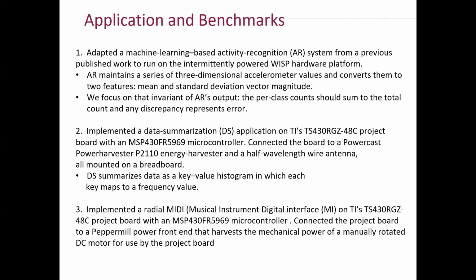In order to test DINO, we need some applications and benchmarks. In this paper, the authors have used three benchmarks. The first is a machine learning based activity recognition system, which they took from previously published work, and they run this on the intermittently powered WISP hardware platform. The WISP harvests radio frequency with a dipole PCB antenna that charges a small capacitor via a charge pump. The WISP has an Analog Devices low power accelerometer connected to an MSP430 FRAM board via SPI.